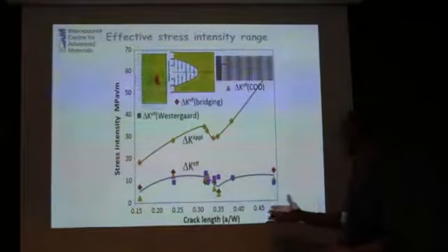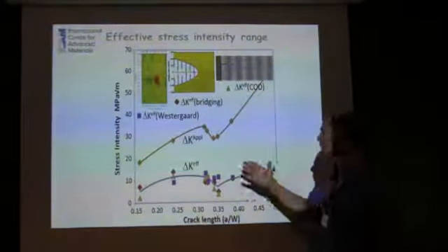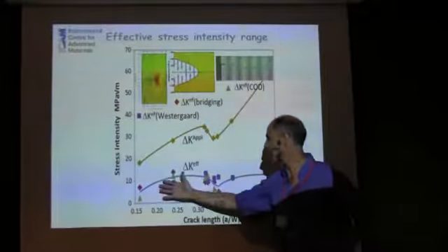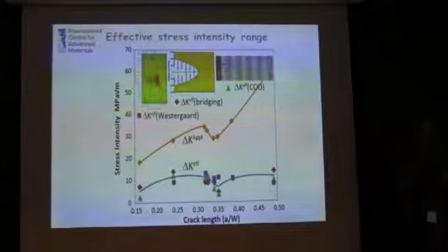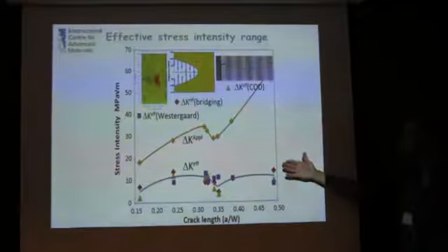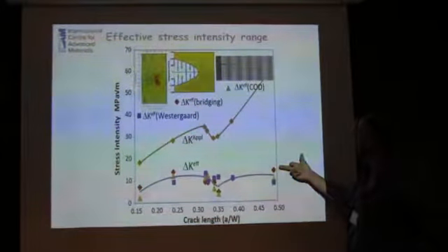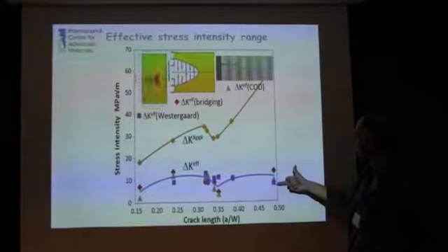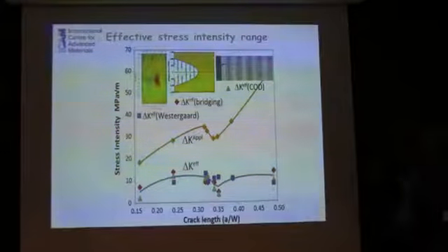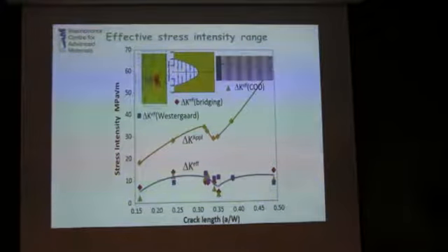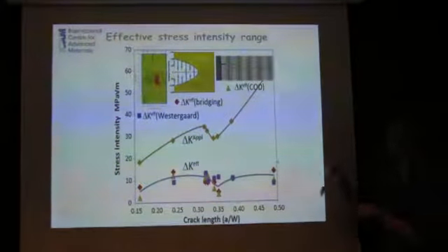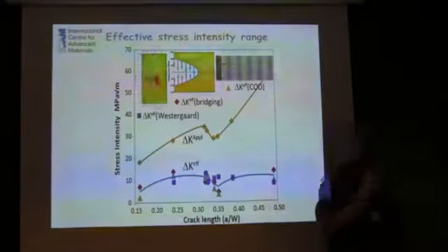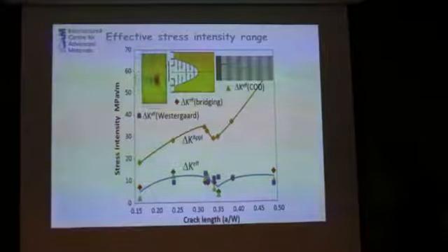And if you compare in all of these cases, as the crack length grows, the nominal stress intensity rises, of course, but the actual crack tip stress intensity stays fairly constant. And you can see reasonable agreement between crack tip bridging, crack opening displacement, and the crack tip stress field solution. So between imaging and diffraction, this was obtained by imaging, these two were obtained by diffraction. You can build a really good picture of what's going on.